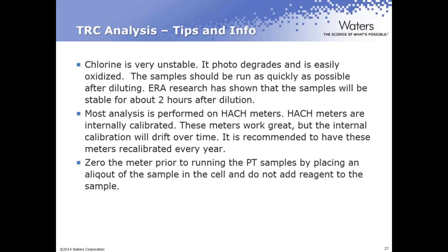My team here at ERA has done some research on how long that chlorine standard can last until you see appreciable degradation, and it's generally about 2 hours. So please make sure you plan properly for running your chlorine analysis, and run that within 2 hours after dilution. Try not to dilute it at the beginning of the day and run it at the end of the day, or especially don't dilute it one day and try to run it the next day.